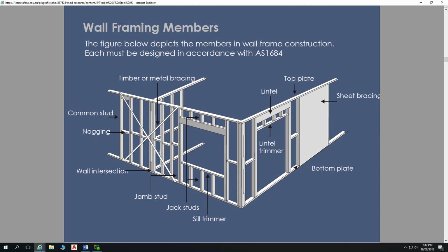Several forms of bracing are shown in this example. This is our Type D bracing, our double strap, which is probably going to be the most common form of bracing that you'll see about the place. It's very cheap. That's made of exactly the same material as typically our strap tie downs. It's made from 30 by 0.8 galvanized iron strap. Your chippies will have rolls and rolls of that on site. They'll use that for their tie downs, and they'll also use it for this Type D bracing.